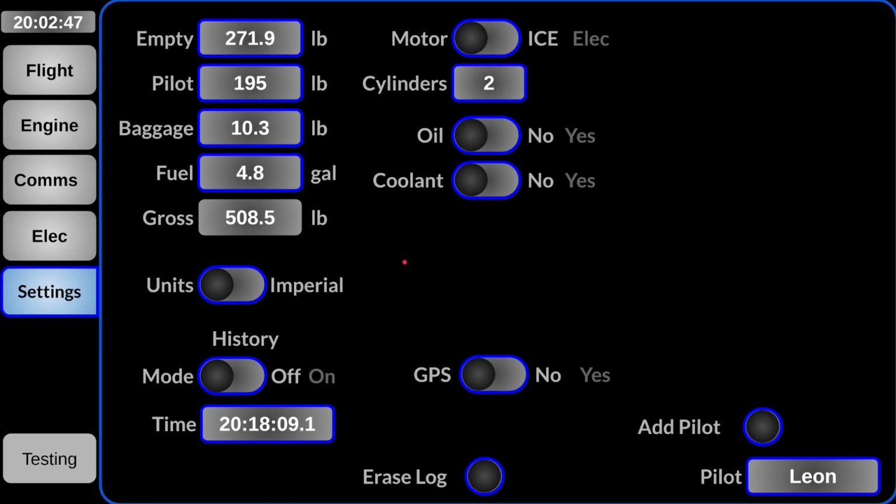Now that brings up another point. Sometimes GPS will have a low quality signal for whatever reason. When that happens, the system has to be smart enough to know we can't rely on GPS, or we're just not getting GPS data, and make appropriate changes to the flight display as that's happening, and to let the user know that GPS isn't available, so we're just doing the best we can, or just not showing some data.